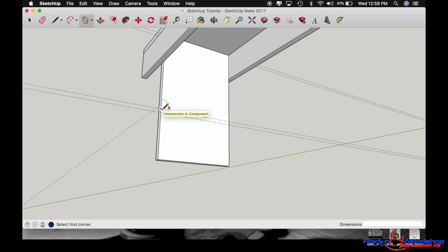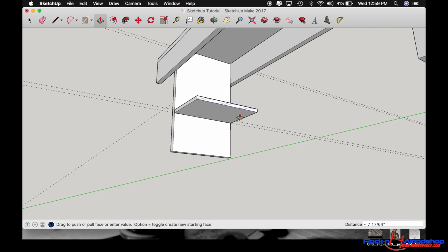Go to your rectangle tool now, and we're going to make a brand new one. So hover over that point and drag after you click, and then click and release. Push and pull, P on your keyboard. Highlight that area and then click. It'll drag out.